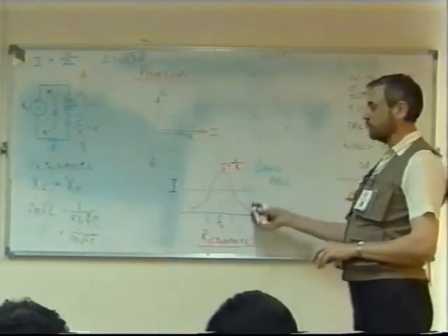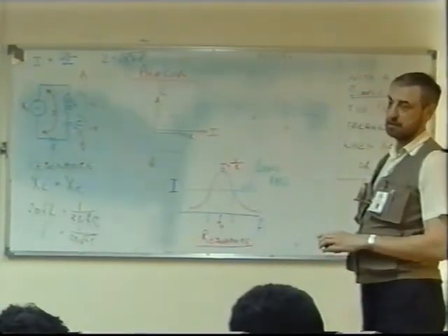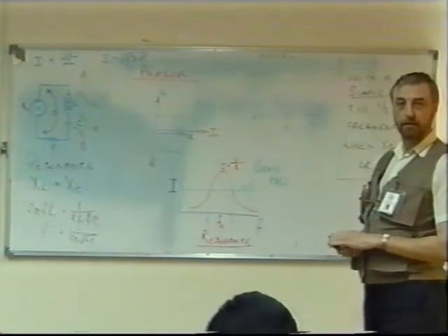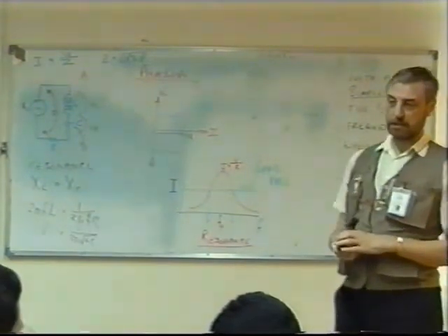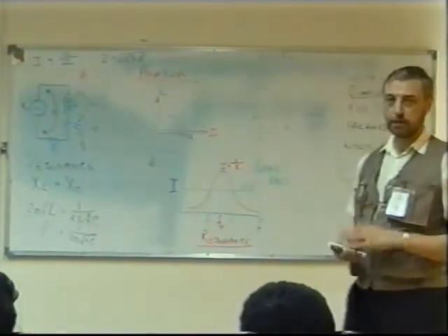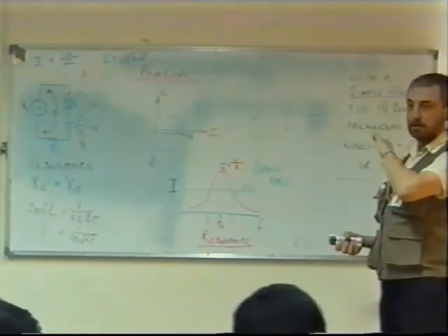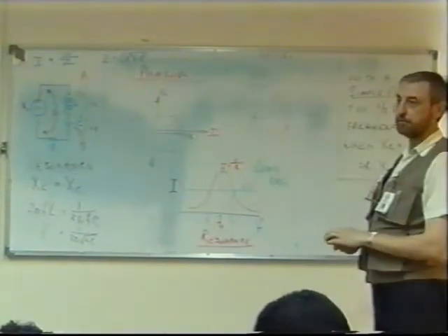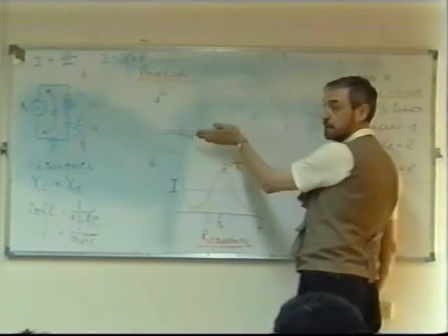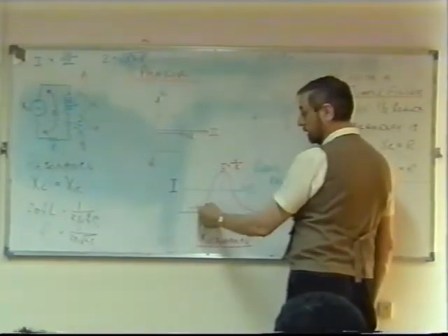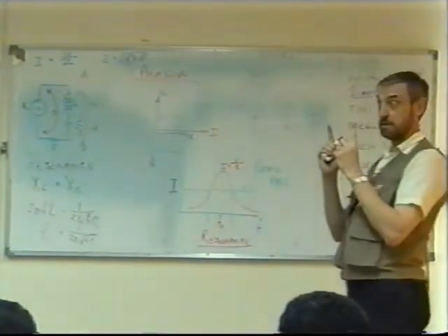So why do you think we call this a band pass band in this example? Okay, well remember how we defined a high pass filter and a low pass filter. We said all frequencies higher than a certain frequency accepted, or lower only rejected. In the band pass, we say that frequencies between these two points are accepted, and lower than F1 or higher than F2 rejected. So it's a band of frequencies, the difference between.